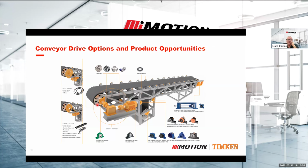Now, the conveyor belts are usually steel cord, so there's a series of wire cables inside the belt to give the tensile strength that they need to be able to drive up. And then on the top of that, you've got what's called the trough idlers. The trough idlers are three idler rollers, so one at the bottom and then two on what they call the wings. And that holds the conveyor in a V form and allows the product to stay inside the conveyor. If it was a flat belt, you'd end up with all the product flowing off the sides of the belt as it moved up.